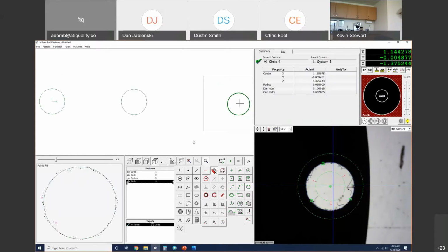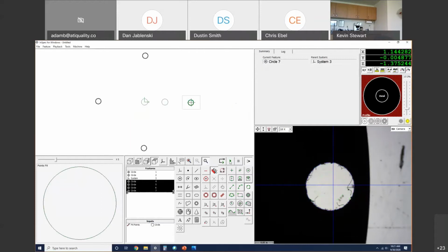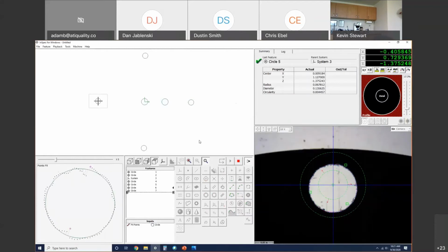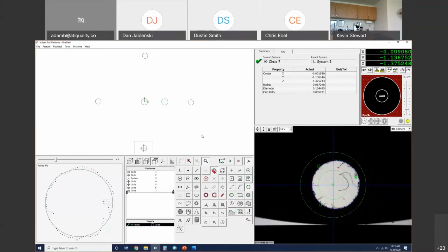Now, usually I recommend taking your first measurement and then renaming it, tolerancing it, and exporting. Since these are all at 90 degrees, rotating about my center diameter, I'm going to go ahead and right-click this diameter here, and I'm going to rotate it real quick just to get all of our measurements. I'm going to do 90 degrees, 3 copies. I'm going to right-click, remeasure. So I got my 4 diameters.